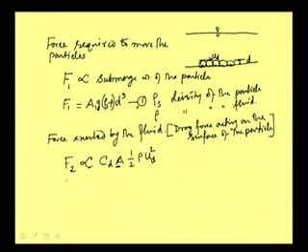So we can write F2 equal to, introducing another proportionality constant A2 which takes care of all the proportionality, CD, then d square, meaning the diameter square, and then half rho UD square. Okay, this is what our expression is.